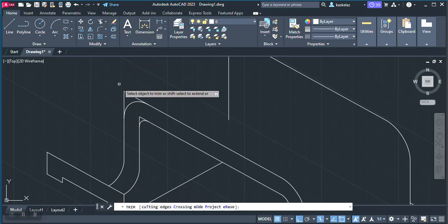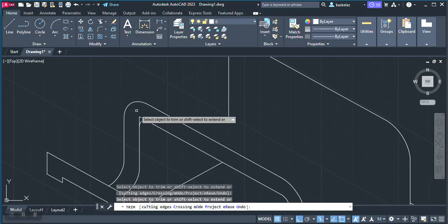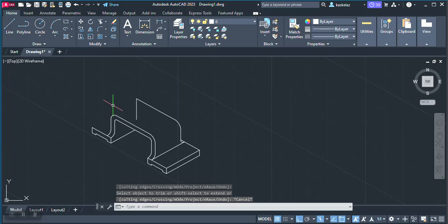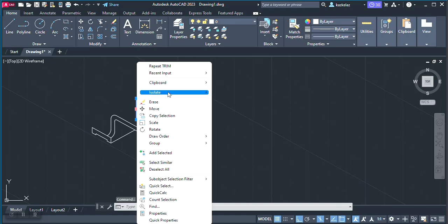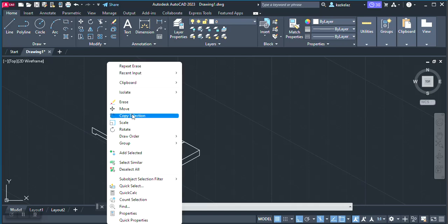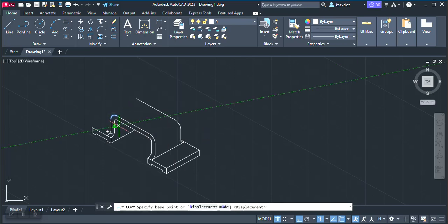So I also need to put, there's some circles that I have. So let me also remove that line, right? And I don't think I'll need it, so let me remove it. There are some circles that I'm supposed to have at the top there. Let's also copy this arc to the other side before we proceed, right? So we know its center is there. Let's copy it using its center, a distance of 68 millimeters, and we are somewhere there. So what we need now is to just trim that part.